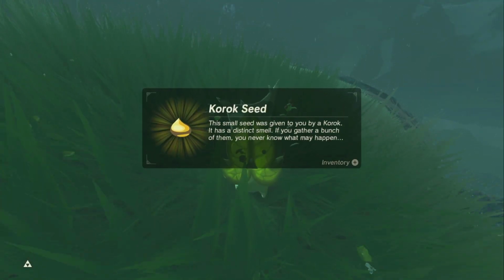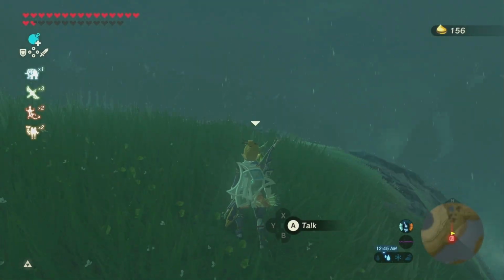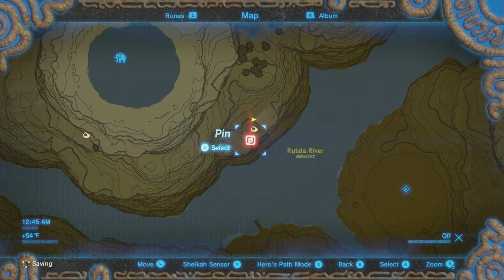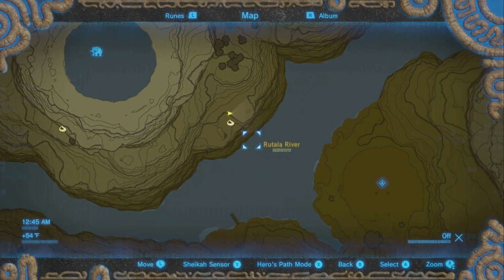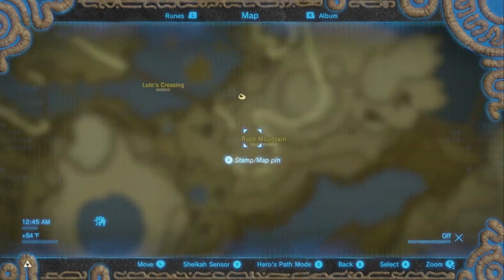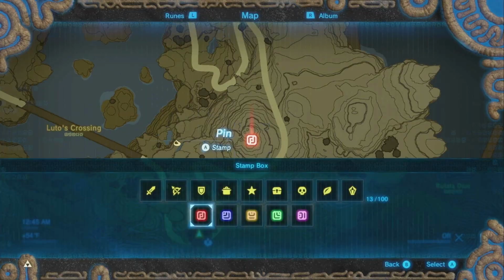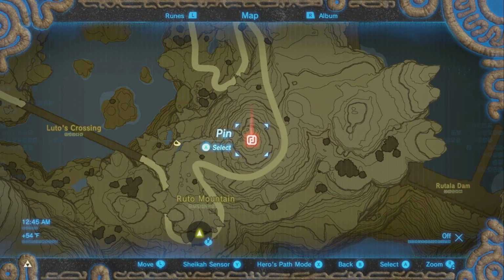Circulating hot water system. The pump may run continuously or may come on when the aquastat senses a water temperature in the return pipe of less than 110 degrees Fahrenheit, for example.